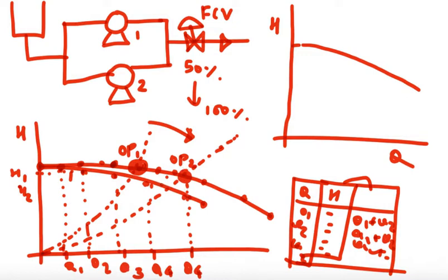So your requirement is to increase the flow rate with the same head. The head will not be lower than your previous single pump operation, but you will get substantially increased flow rate while you are operating your pump on the right side of the pump curve.